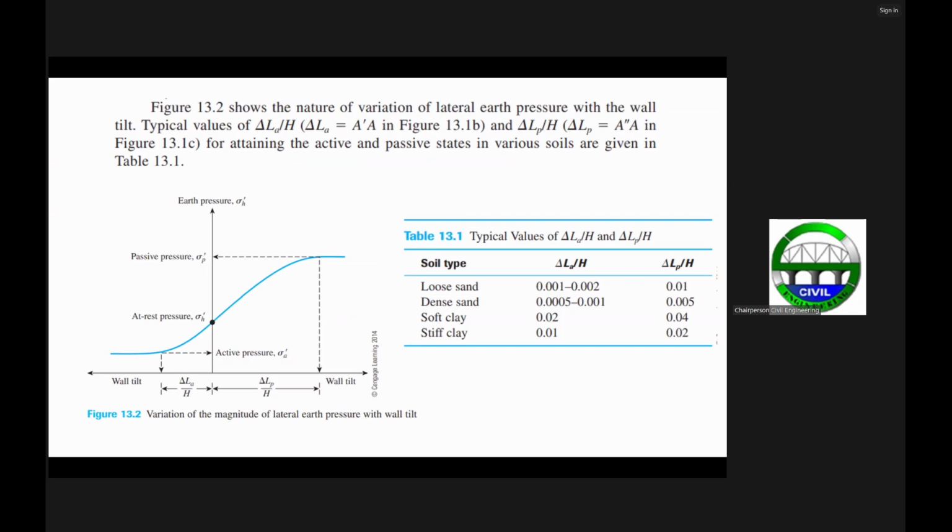These are stiff clay materials. Normally, if you excavate through stiff clay, it can withstand vertical cuts for a longer period of time. That can be a visual observation of a stiff to hard clay material.